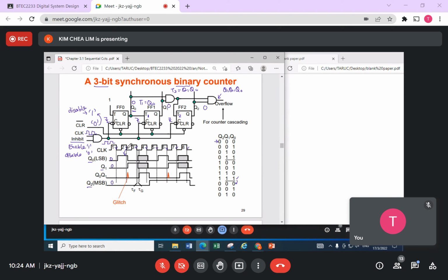Clock pulse number 2 comes, and they check what is waiting in front, the signal waiting there is a 1. Remember the setup time? If the setup time is sufficient, they see the 1 and then they are going to toggle. Whereas here is a 0; they see a 0 waiting here, so don't toggle. Sorry, I made a mistake here.